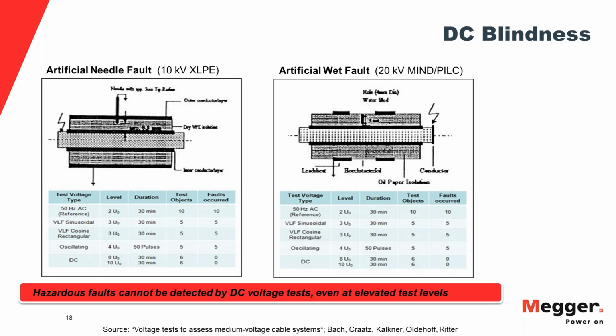Many people assume that with chain molecules everything is in order and straight and looks really nice. The truth is, on the molecular level, it turns more into spaghetti on your table. It's not so straight anymore, and not all the molecules are orientated in the same direction. So you have pockets available there. By the way, these are also the pockets where the moisture can come in and stay in the cable. And this is exactly where you trap these space charges.